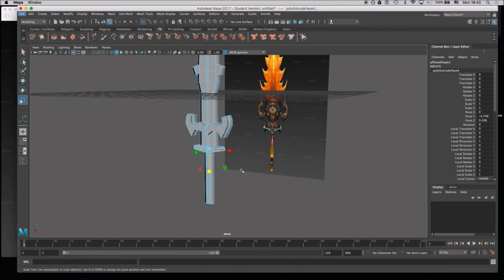Can I select all of the vertices? Oh, there we go. The top layer, all the same height basically? It got bent for some reason. What I would do is grab all the faces that are on top, and then scale it towards how you want it to be. Like if you want it to be flat, you scale it down in that direction, and then it'll flatten out all those faces. I can show you really quickly after this.